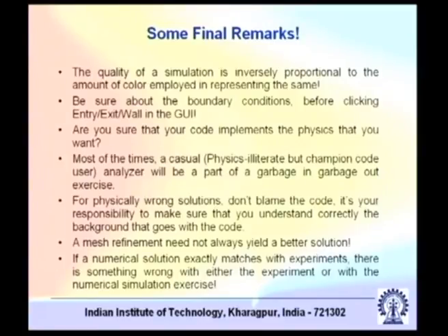So if the PDEs are possible to be cast in a general conservative form, then only is your CFD code possible to be implemented for the particular problem that you are addressing. If you have equations which do not fall into that category, simply do not use that code. Try to use a different code or develop a code or whatever, but do not use it.